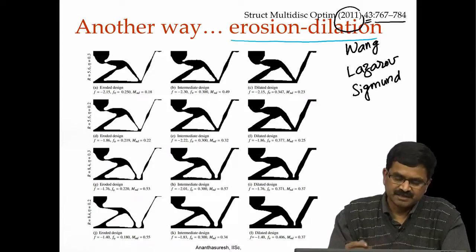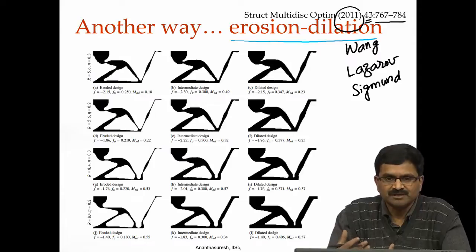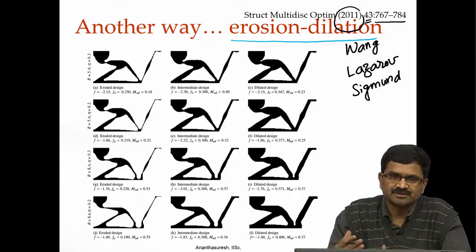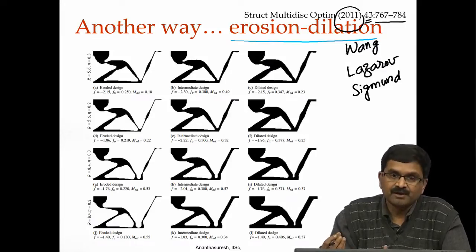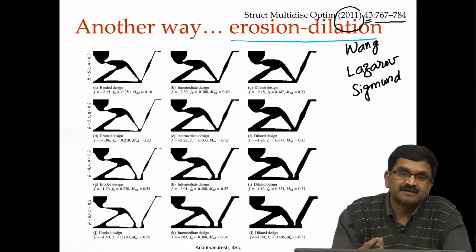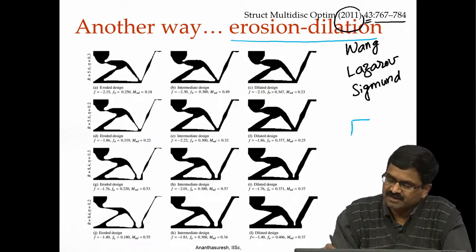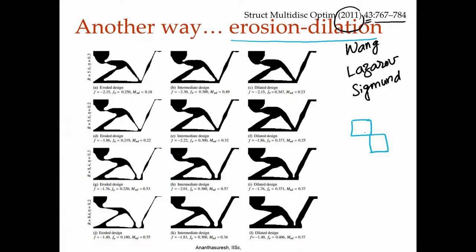What they do is, let us say in the course of topology optimization, you have all the indicator functions rho everywhere. Every element that you have, you erode it a little bit, meaning that you make it thinner. If I have an element like this and an element like this, you make this element a little bit smaller, rather the width or whatever. You can see compared to this, this is a little bit weakened, as if it has not eaten for some time. It is eroded, whereas this actually has become fatter, it is fed more.